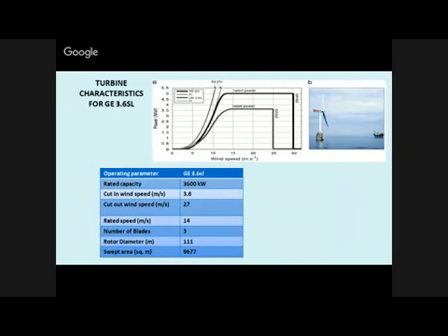Then normally a blade is optimized for 3 blades. So that's why it's 3 blades. In most cases now, 3 blades are used. The rotor diameter is around 111 meters. At 80 meter height, the radius will be around 55 and the diameter will be 111 meters, almost equivalent to a football ground. Then the swept area based upon the diameter is 9,677 square meters. This kind of size is available, and people are even going for bigger than this.